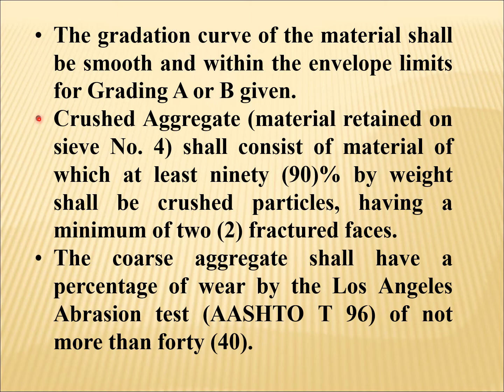Crushed aggregate material retained on sieve number 4 shall consist of material of which at least 90% by weight shall be crushed particles having a minimum of 2 fractured faces.